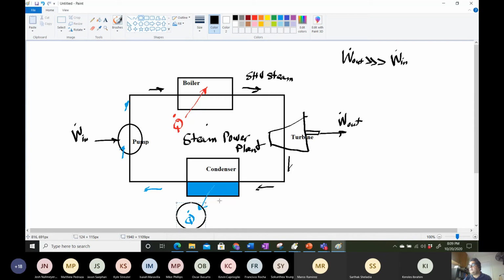One thing, I'll talk about this more next time, but this is necessary. You can't complete the cycle without condensing and pumping, because a pump only pumps liquid, it can't pump vapor, right? This is still necessary. We have to throw away energy. You have to throw it away. So the work that comes out of the turbine is never 100%, never could be, not even 90% efficient.